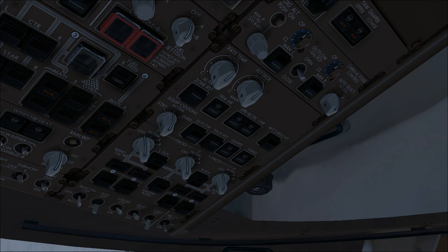So when you release the air into the cabin, you should actually improve the humidity of the air itself to around 40-50%. Anyway, the humidity is not modified usually in the aircraft, because if you increase the humidity, you can actually create corrosion problems on the airframe itself. So usually in the aircraft the humidity is not controlled.